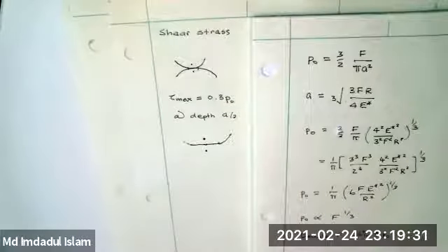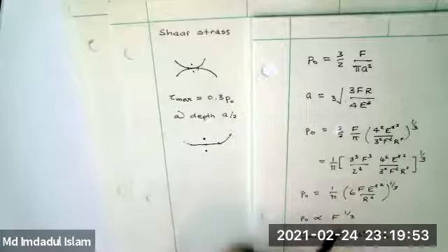That's because the contact region spreads in 2 directions. And so that's mitigated. When you doubled F for roller contact, it could only spread laterally, not the out of plane direction, which stayed fixed. And so that mitigated it, and it meant that the maximum contact stress went up as the square root of F. But here, it can spread in both directions, and so you get the cube root here.